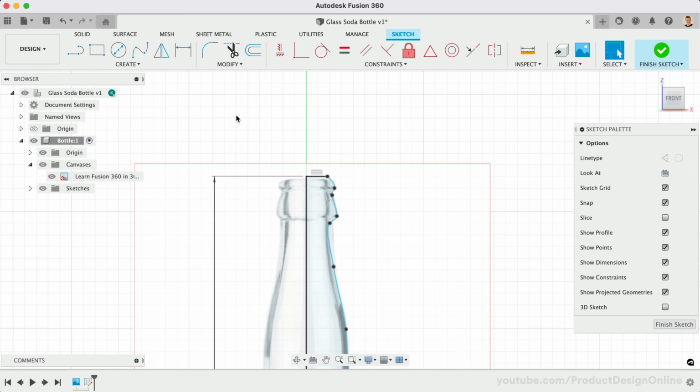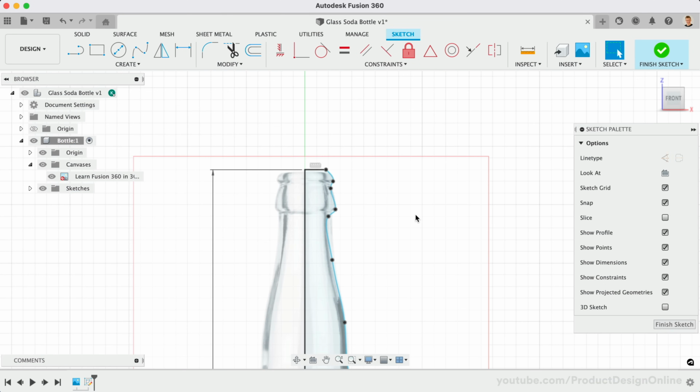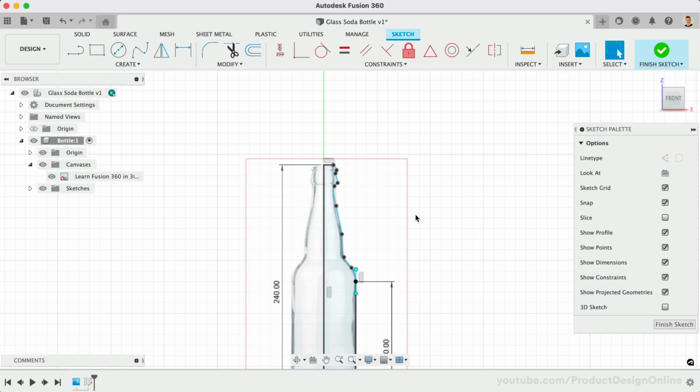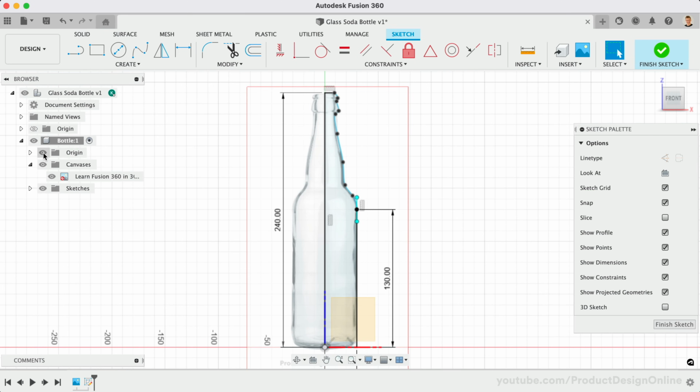After fully connecting our shape, you may have noticed that our shape now has a blue background highlight. Blue signifies that we can use the profile shape with the solid modeling commands. Many commands, such as the Revolve command, require at least one closed sketch profile.